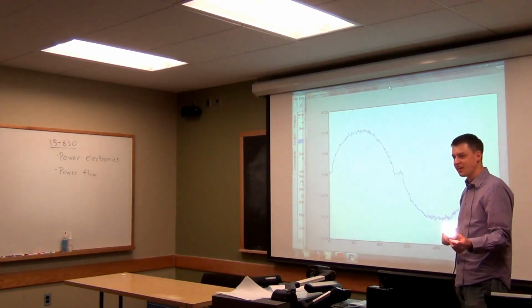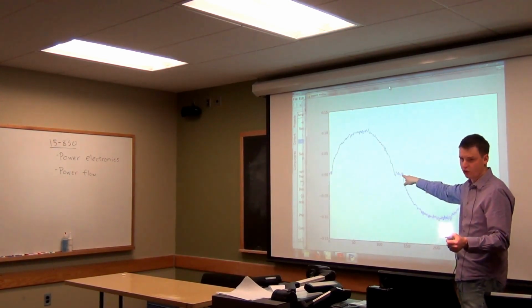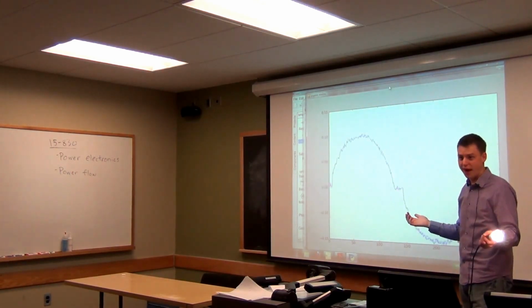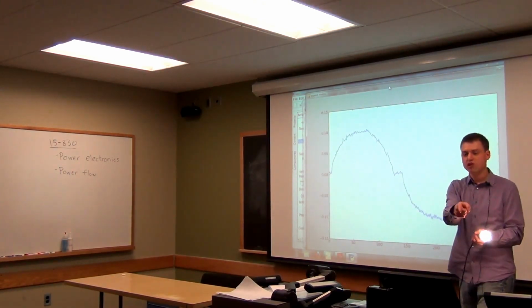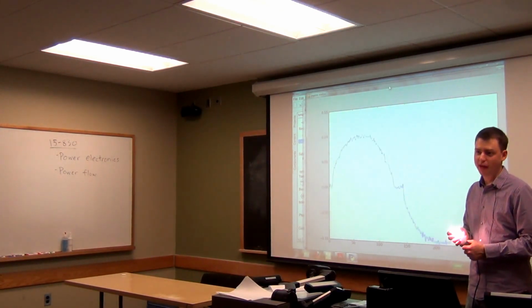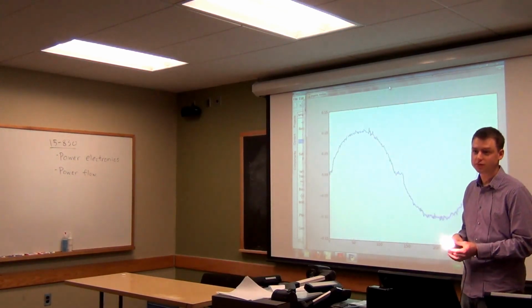I can check that. I'm not sure that's actually what's going on here. It might alternatively be shaping this to look more like a sine wave, because that's, again, a good thing for large consumers of power to do. But this looks like what you would see if you just have that rectifier without a very big capacitor on it. So always going one direction through it, but taking different amounts of voltage.